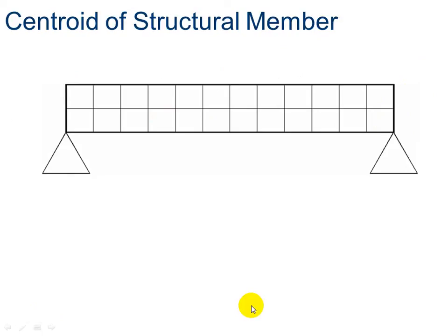In order to calculate the strength of a structural member, its centroid must first be calculated. If the member is subject to pure bending and its stresses remain in the elastic range, which we'll talk about in a few lessons as well, then the neutral axis, when seen in 2 dimensions, or the neutral plane, if we look at it in 3D, this axis right here, of the member passes through the centroid of the section. So the centroid is somewhere on this line right here. The centroid is an ordered pair in an X and Y position. And the centroid's always located on an axis of symmetry.